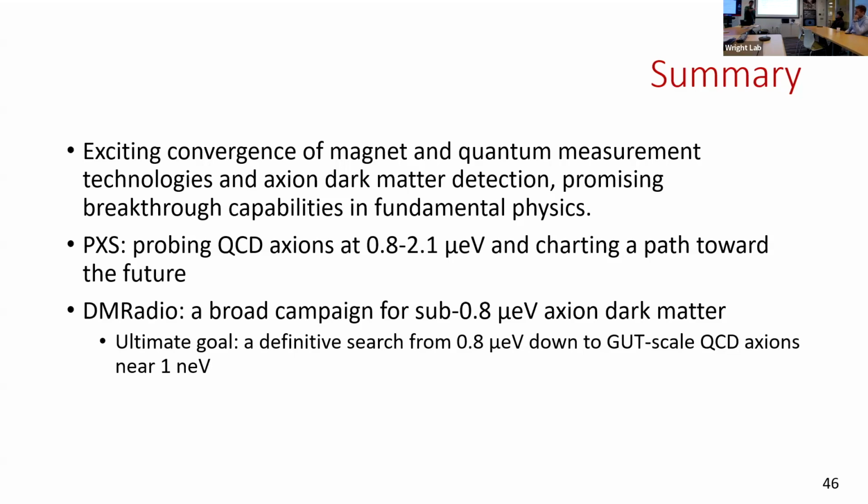And then if I push in the other direction of using smaller A over L, I bottleneck the natural thermal flow, but then I have high resistance, I have high joule heating. So there's an optimum. It turns out for a given current, there's a particular ideal A over L ratio, and it corresponds to when there is no net heat flux at the top.